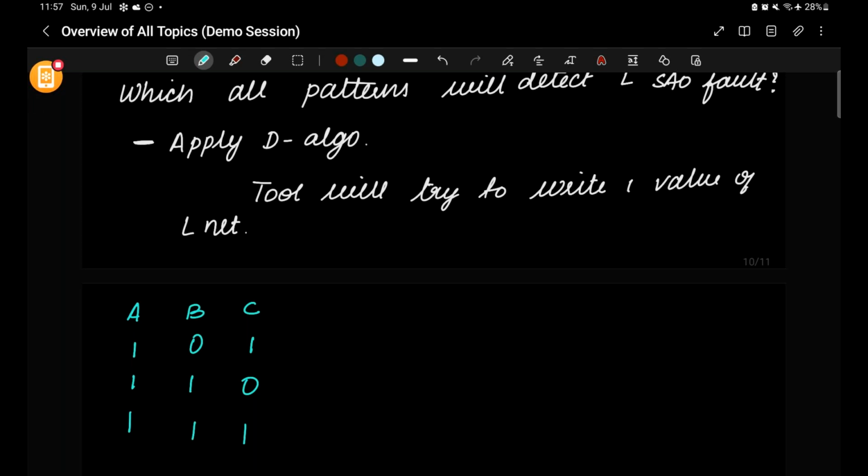In the same way, a few more questions you can expect in ATPG: as we have done for stuck-at, they might ask for transition delay fault which pattern will detect it, and the 2 ways of detecting transition delay fault, that is TDF LOC and TDF LOS. Then what is the difference between the transition delay fault model and the path delay fault model, what is IDDQ test, what is burn-in test. In OCC also you can expect: which logic decides which clock has to be propagated during shift phase and capture phase, and also decides the number of clock pulses during capture. So OCC also they can ask.